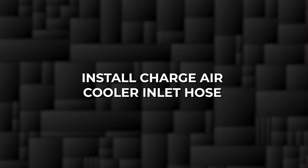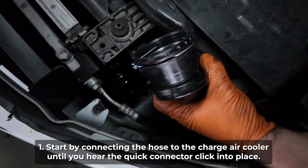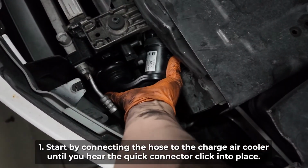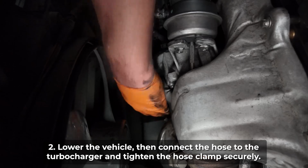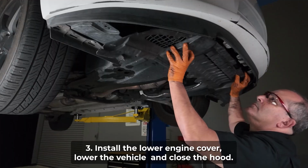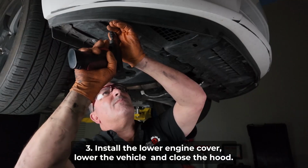Next, install the new charge air cooler inlet hose, the hot side intercooler hose. Start by connecting the hose to the charge air cooler until you hear the quick connector click into place. Lower the vehicle, then connect the hose to the turbocharger and tighten the hose clamp securely. 3. Install the lower engine cover, lower the vehicle, and close the hood.